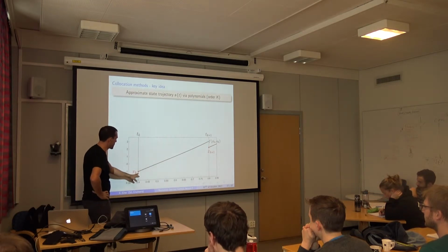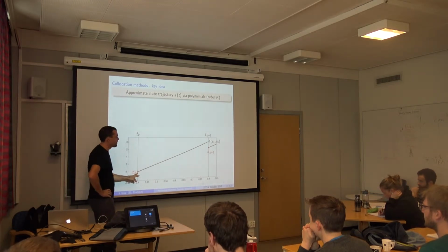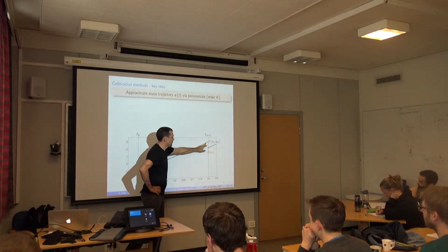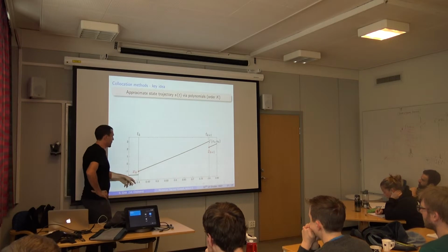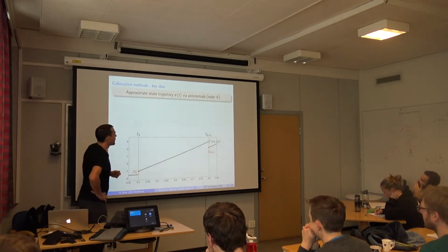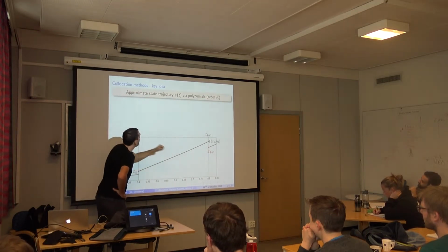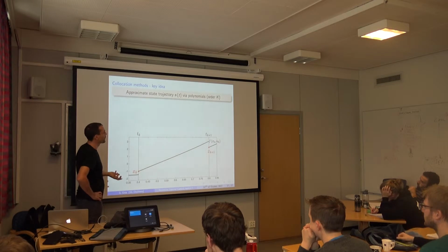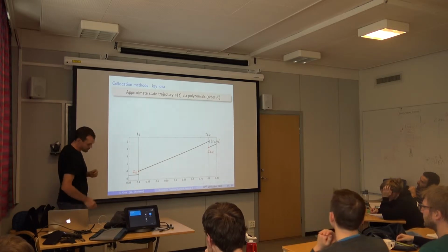The initial conditions are variables in the NLP solver, and you need to build that trajectory that simulates the system on that time interval. And that's for one state; you may have a number of states. So that's your S, and in collocation methods you would want to approximate this S by polynomials of a certain order.